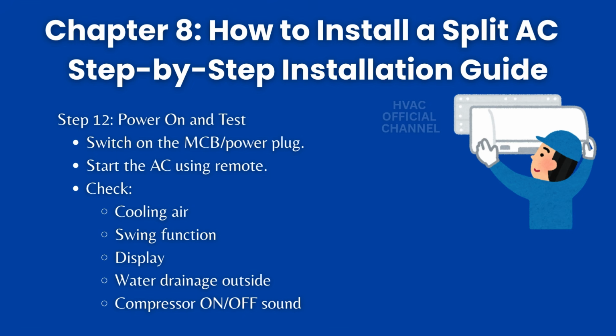Step 12. Power on and test. Switch on the MCB/power plug. Start the AC using remote. Check cooling air, swing function, display, water drainage outside, compressor on-off sound.